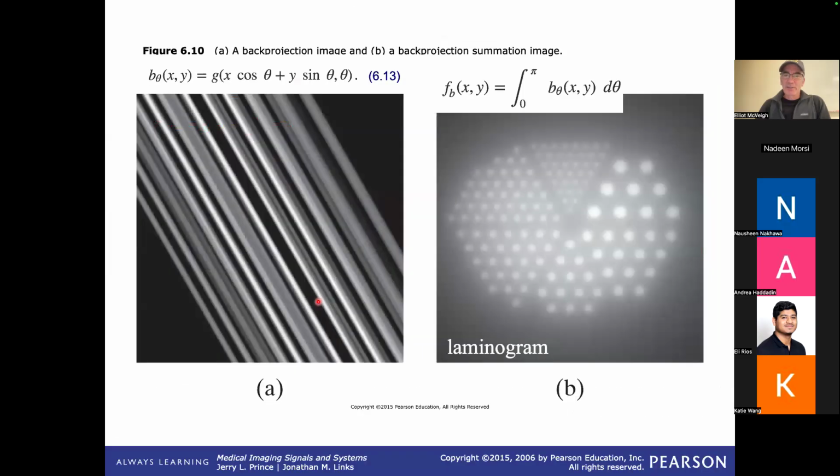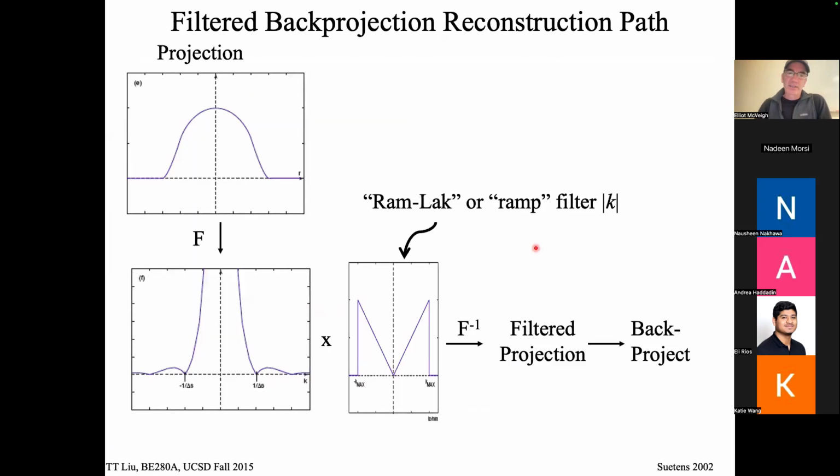Okay, we can do some other things. So we can take that sinogram for each one of those functions, we back project it, and we get this crappy picture. Okay, it's a picture, but it's not a great one. What we have to do instead in CT is we take our projection data, right, and we look at it in Fourier space, right? We take the Fourier transform of this data, and so it gives you spatial frequencies as a function of position along here.